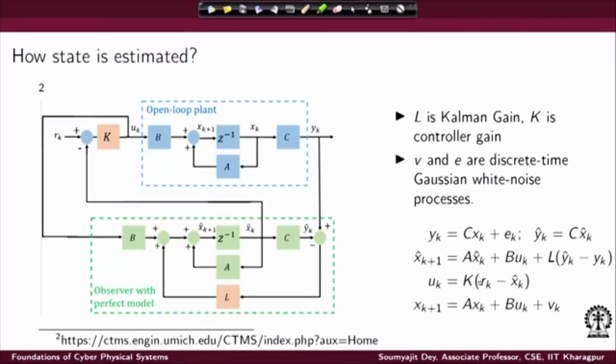Okay. In case your reference is 0 in this place for the controller, it is simply our standard equational form, that is minus k x k, but instead of minus k x k you are having minus k x k hat. So, that is the more practical scenario, because we can't expect my controller, like I was saying, that it is going to have access to x k, right.